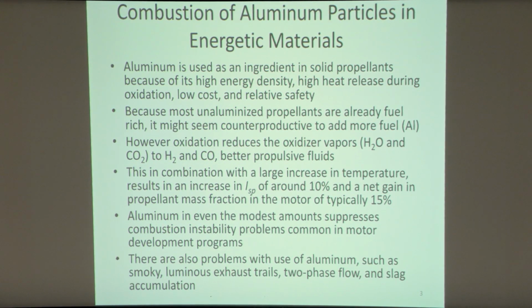Aluminum, even in modest amounts, suppresses combustion instability problems common in motor development programs. However, there are also problems with the use of aluminum, such as the smoky exhaust, two-phase flow losses, and slag accumulation, for example, if it was used in a motor.